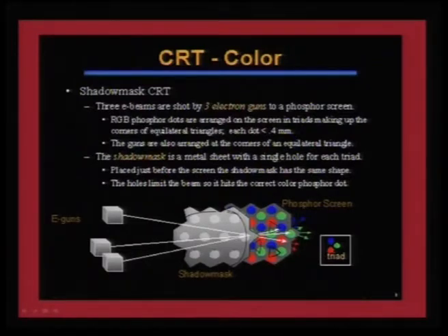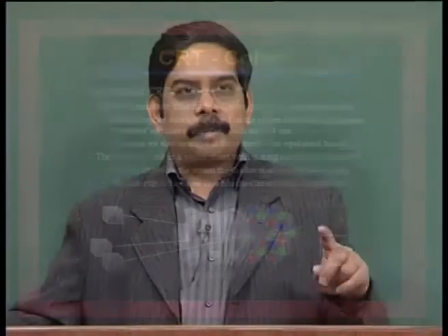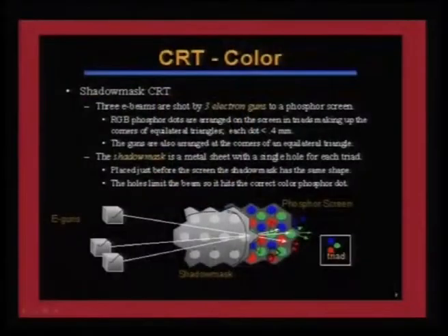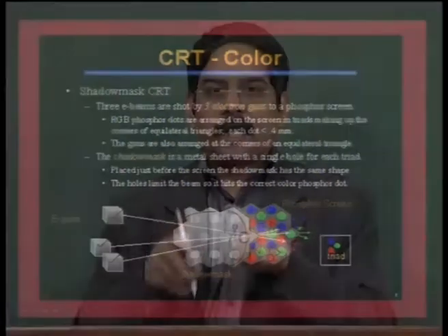So, if you want more of red color dominance, then you need to pump in more cathode ray energy, so that you get this on a brighter proportion compared to blue and green. So, in a color monitor you actually have 3 electron guns doing the job, and each of this gun will go through one single orifice in the shadow mask, which will in turn do the right color mixing.